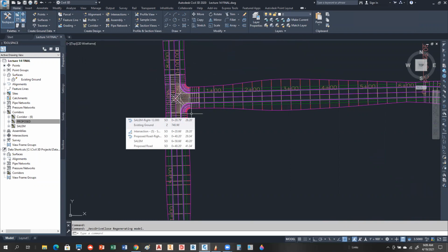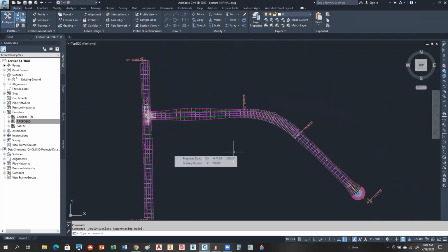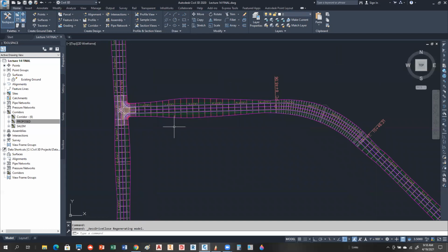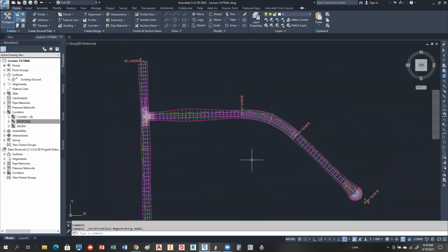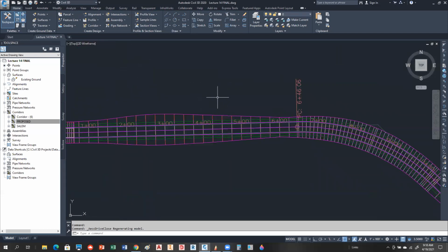Okay, McAllister, we're going to hit your question. We want to build some surfaces here, and then from those surfaces, we want to create some contours, okay? So what we want to do, does anybody remember how to build a surface out of a corridor? Let's try that first. It's just create surface, right? Under surfaces? No, it's not quite that simple.